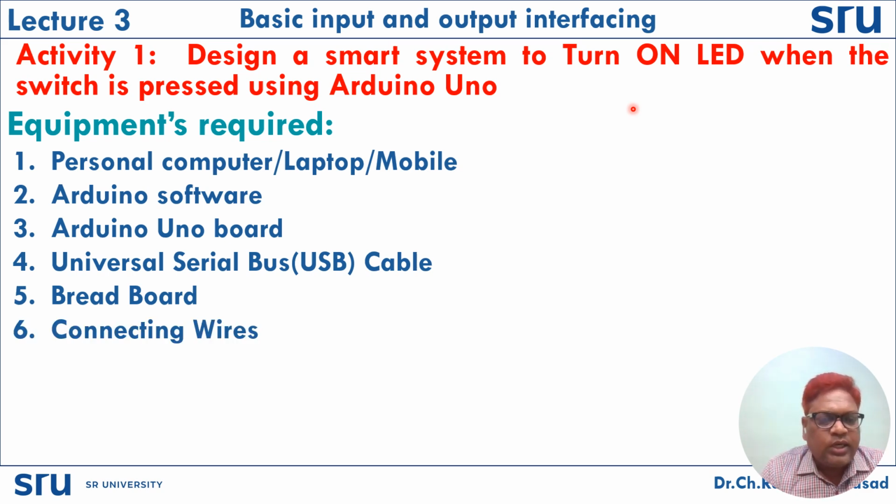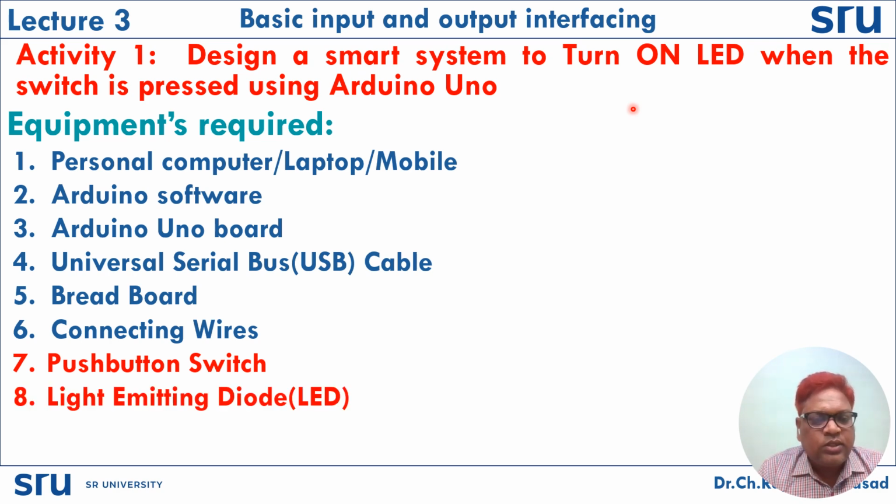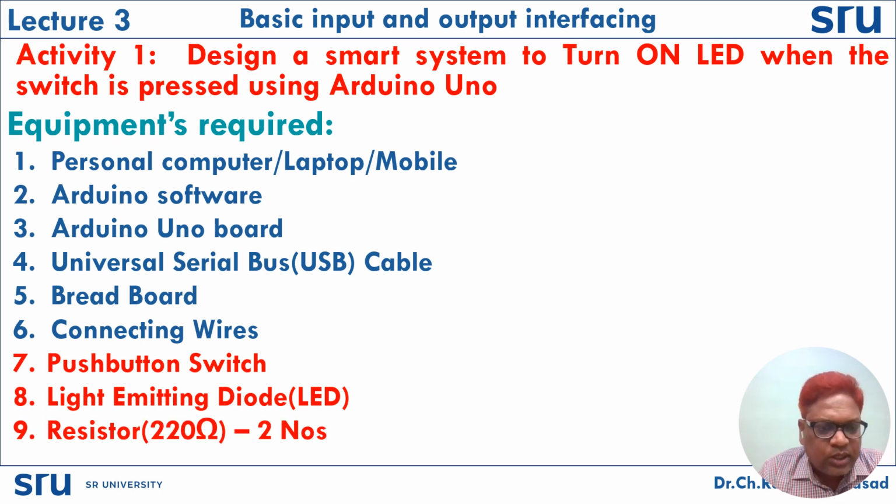Then some connecting wires are also required, and a push button switch and light emitting diode. These are the components which we require for our application. In addition to this, when we are using a light emitting diode or a push button switch, we require some resistors. So I am considering resistors of 220 ohms, two numbers.